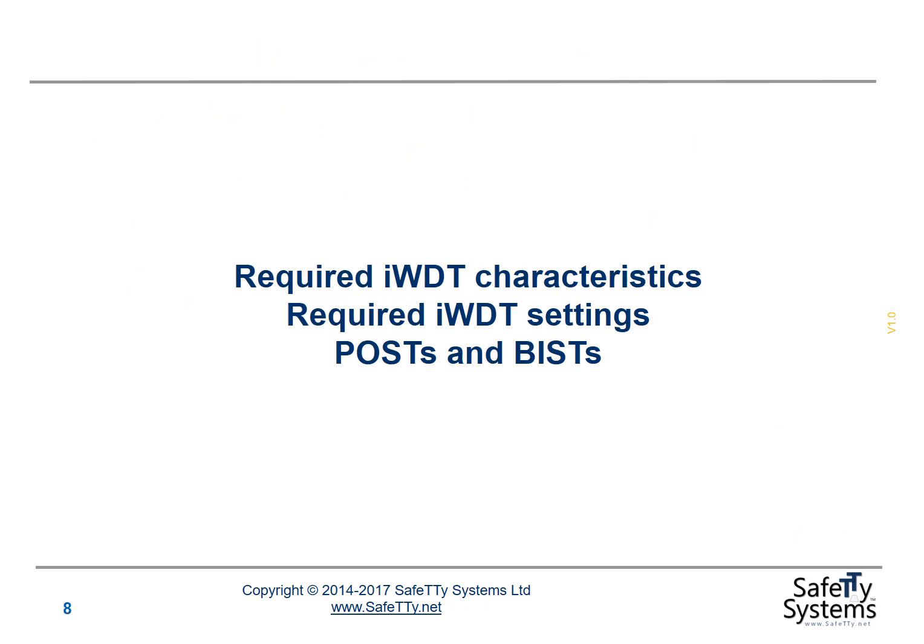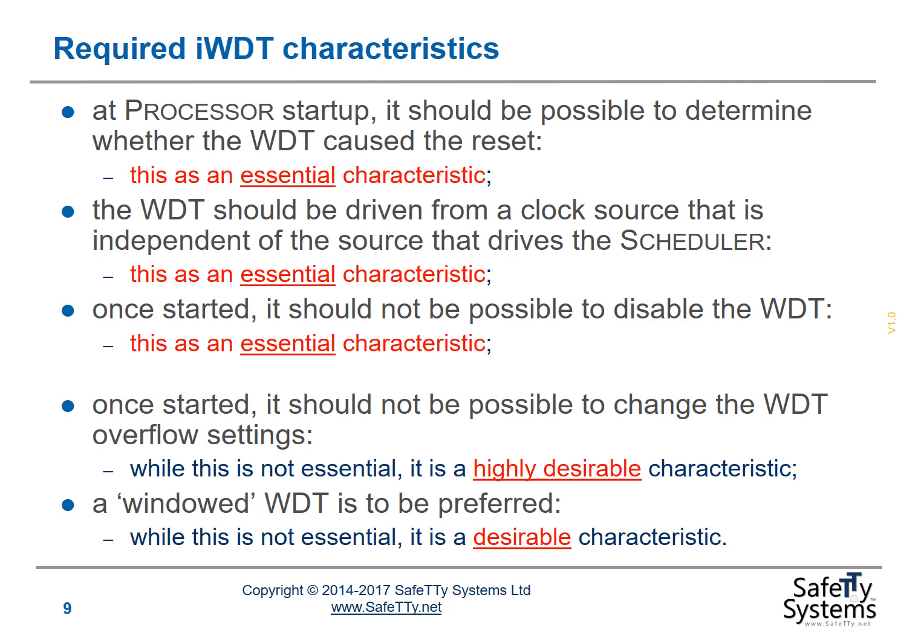So let's consider the required watchdog timer characteristics and the required watchdog timer settings, plus the need for power-on self-tests and built-in self-tests on the watchdog component. So these are our required watchdog timer characteristics. As we've touched on previously, at processor startup, it should be possible to determine whether the watchdog timer caused the reset. I see this as an essential characteristic of watchdog timers for use in reliable embedded systems.